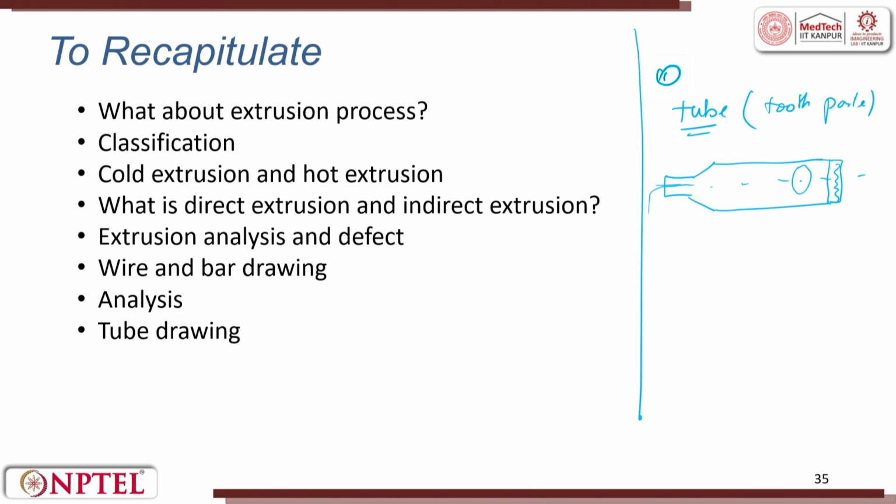Only at this point, after a major portion is done, you will see a lot of residues here and there. Then what do you do? You try to put a roller here and then you try to squeeze out. When you put a roller here and squeeze out, a small amount of material comes out. This clearly states that there will be residue there, and this residue has to be pressurized and exit. If you do not do this operation, there will be some residue which is waste.